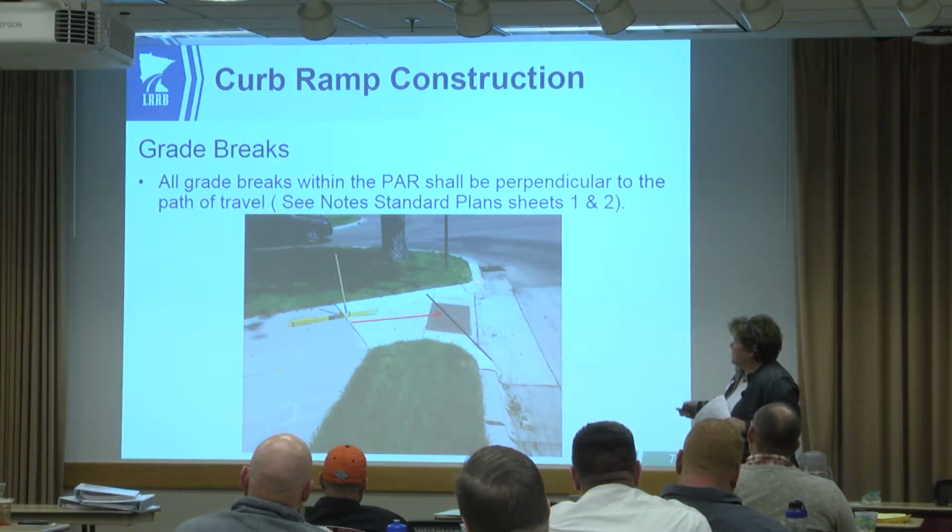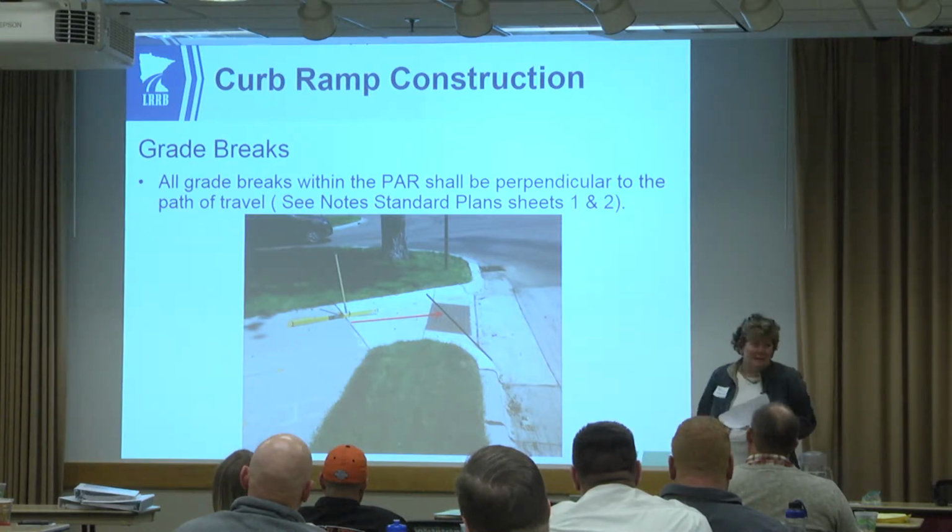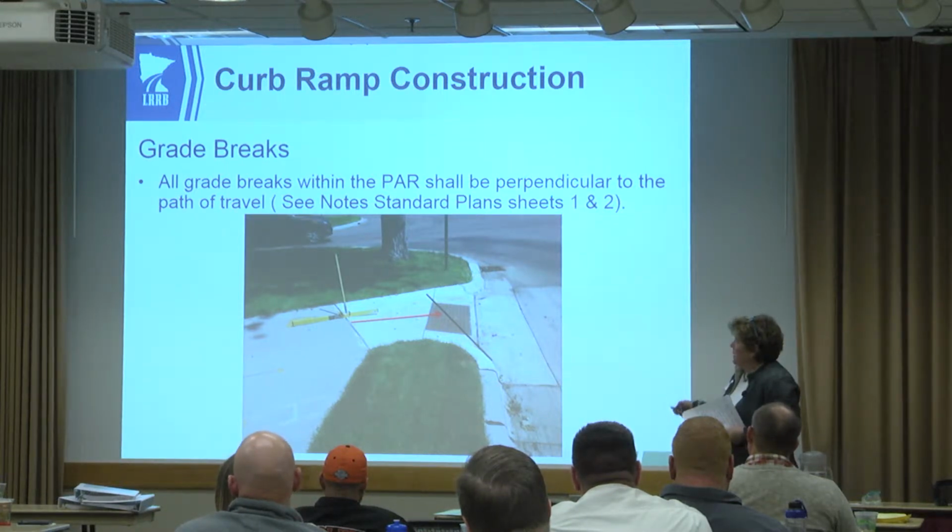So this is that section where we're supposed to place this integral with curb and gutter. And this panel should be placed transversely here when we get the first full width section. Here's a great example of how we're on a skew, so every curb intersection is different. This does not match up with the standard plate because we have a funny return radius here, but we are indicating this would be a good place for you to have your joint go across here.